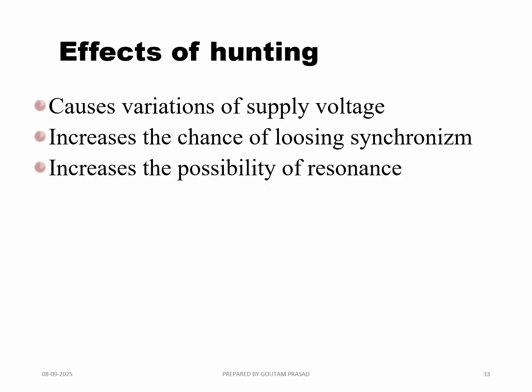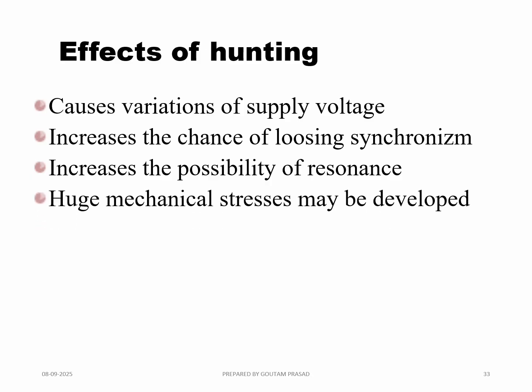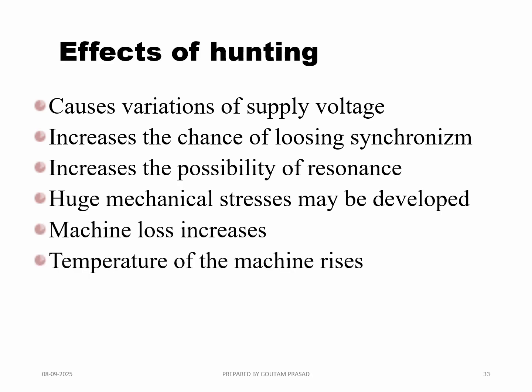Resonance is the condition when the natural frequency of the material with which the rotor or stator or the whole machine is made matches with the frequency of oscillation in the case of hunting. So that's a very devastating condition. It can break the foundation bolts if the resonant amplitude is very high. So huge mechanical stress may be developed because of this. Machine loss increases, and temperature of the machine rises.